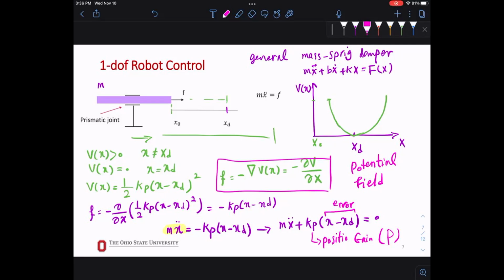So here, I have a prismatic joint, right? And I need to stop at some specific x desired. I created a controller, a force, an input that I know I have to pull, right? It goes back and forth. Maybe it starts doing this very close, but does not stop. So I need to create another expression and make sure this will stop. Makes sense? So you are able to move it. You're able to be very close around where you want to be. Sometimes just tuning this, you might be able to stop. But in case you didn't, you need another expression.